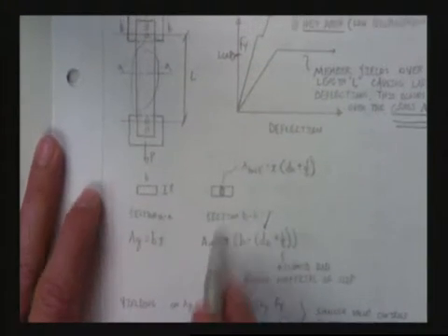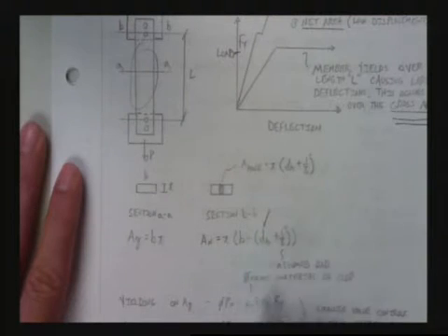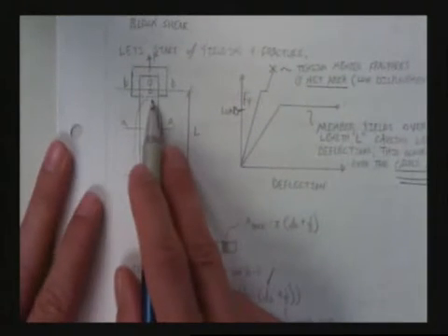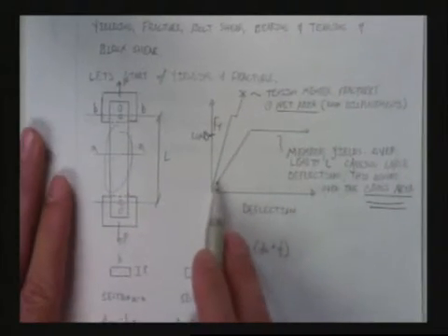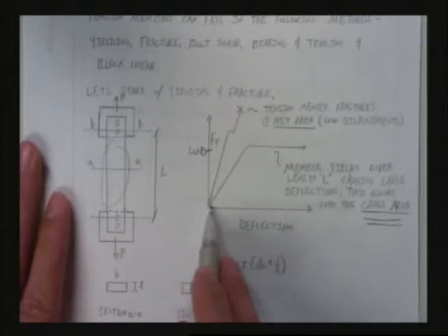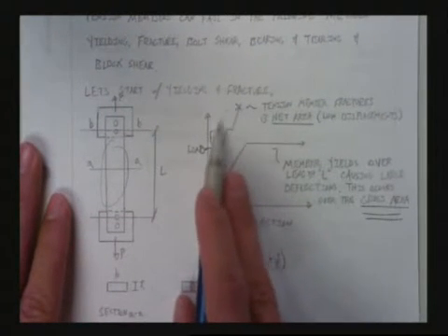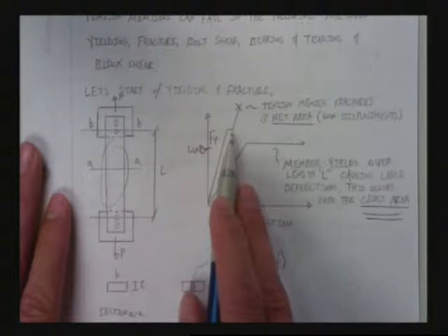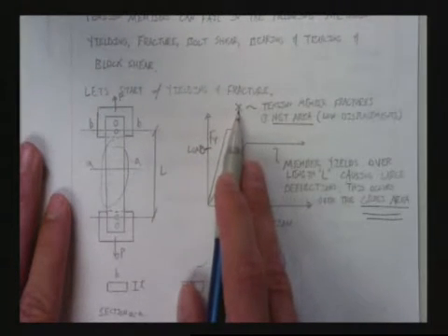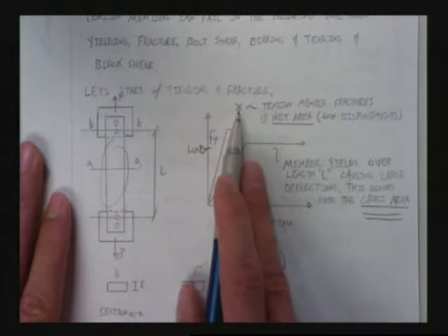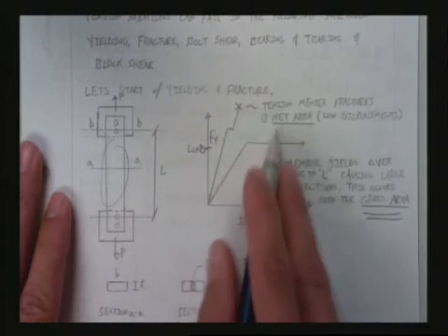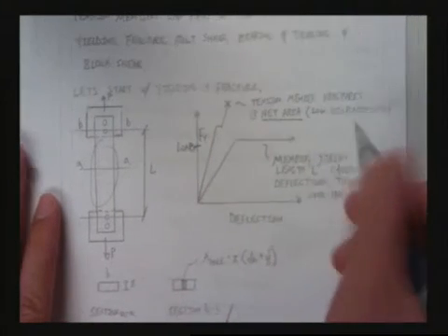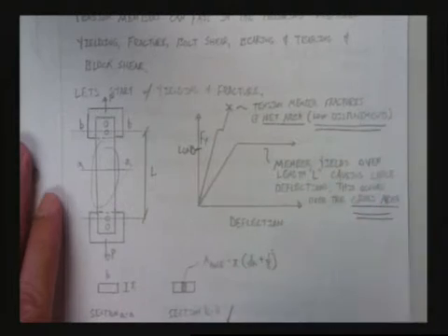There we go. There's the area of the hole is this. There's the area net. So this fracture is happening here, and our load deflection curve looks something like this. It goes up, but it yields, it quickly goes up again, then it fractures. Okay? That's what happens. It breaks. And this break happens at low displacements.